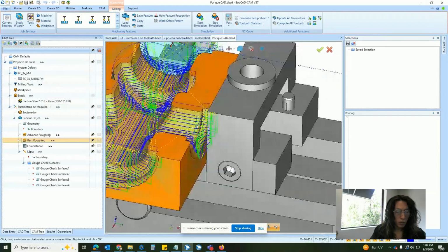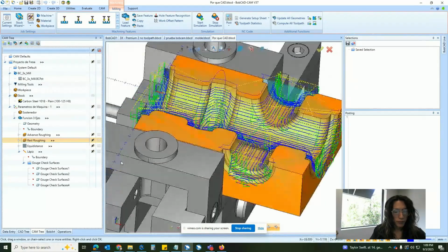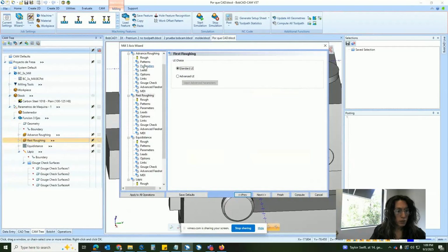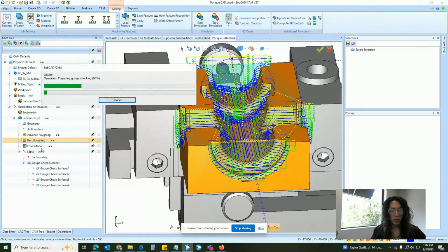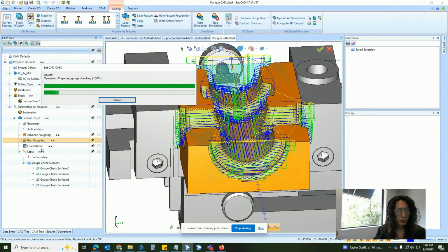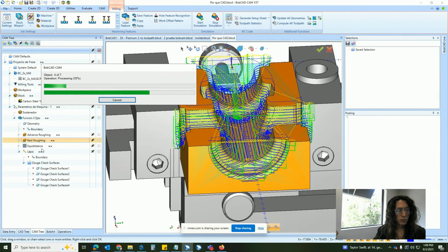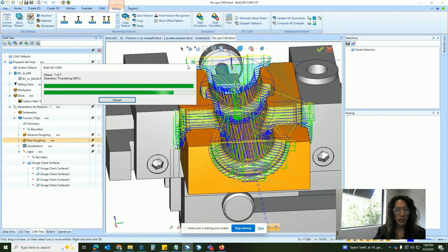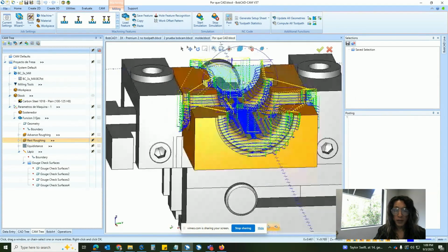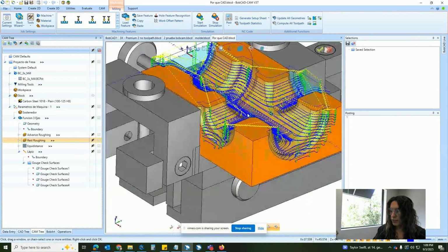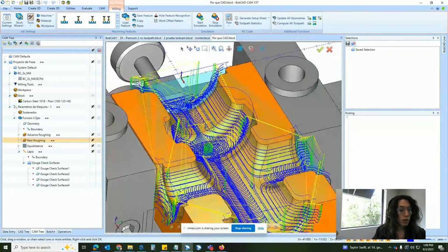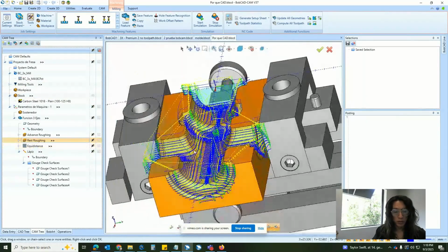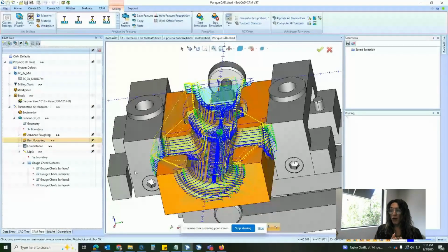And you'll see how, let me do an advanced roughing operation. Make sure that we're using the advanced. Finish, recompute. So we have the same. Also, something you're going to notice, the time it takes to do our toolpath, it's actually pretty fast compared to prior versions. So again, we have less retractions and we are removing those collisions.